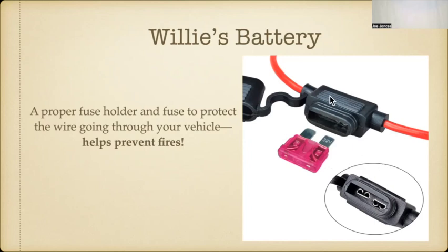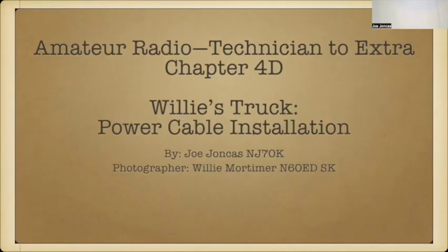So these fuses will take a lot of current, and they will not drop your voltage nearly as much as this other style of fuse. Because you don't want that, in 12 volts, if you lose a half a volt, you're down to 11.5 volts, and your radio is barely working. So, here I'm going to show you this video and then make some comments later.